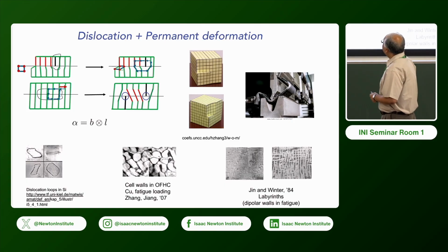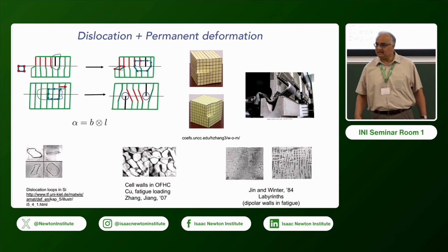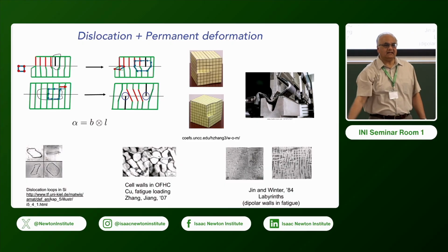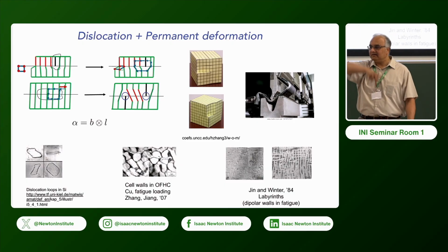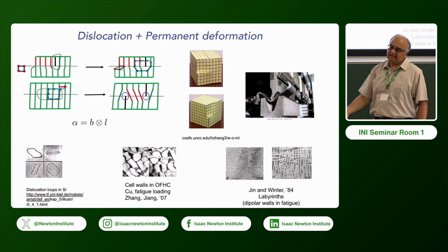And now you do the same thing on an undeformed lattice. So you go 3 this way, 2 down, 2 this way, 2 up. Of course, there's going to be a deficit because you have 1 atomic plane missing there. And you can right away see that no matter how big a loop you do this on, because that atomic plane is missing, you're always going to get this deficit.